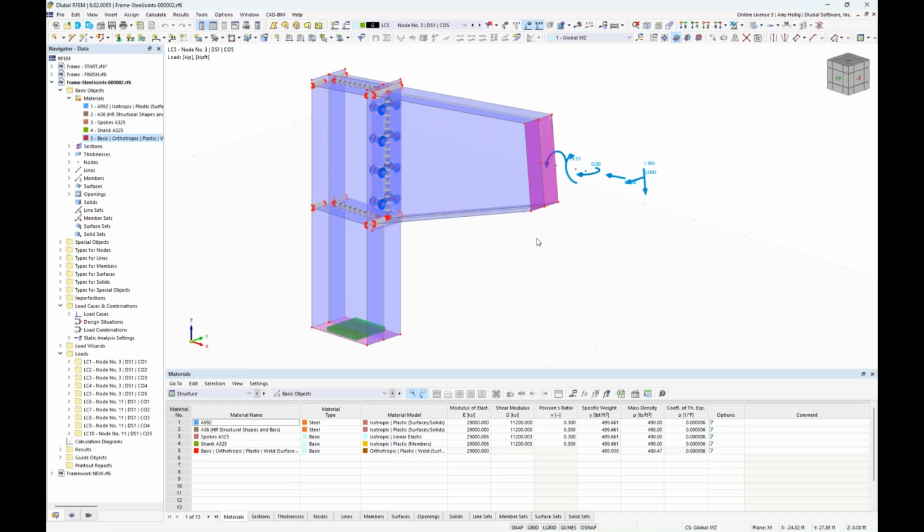So we don't have to worry about topics like singularities because this load is distributed again to the entire face of these elements. And remember too, that we had to set at least one supported member. Well, we can see that support applied here at the bottom of the column. Okay, so that will cover here just the submodel.